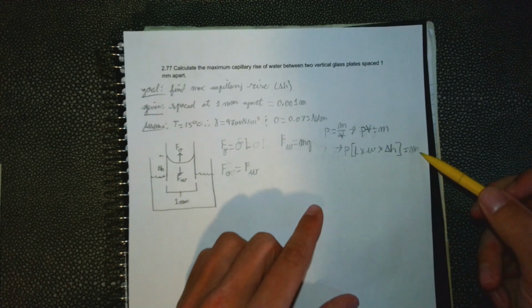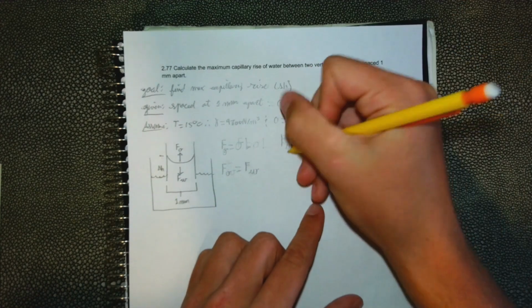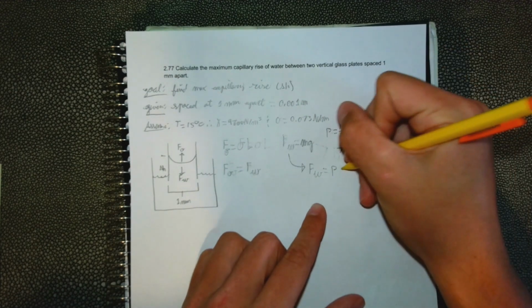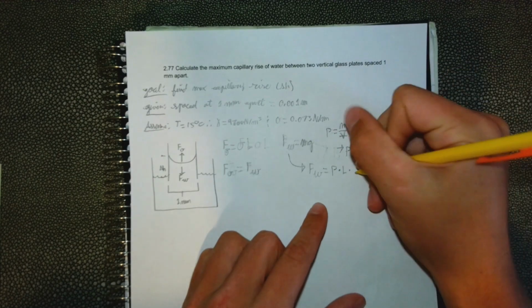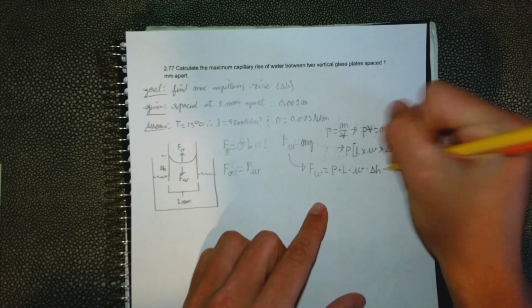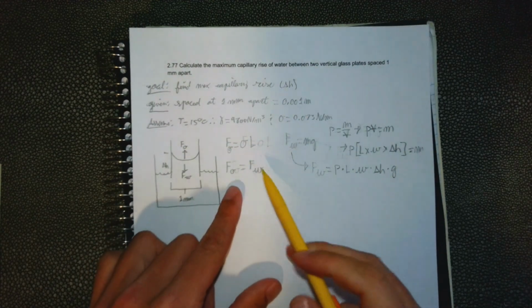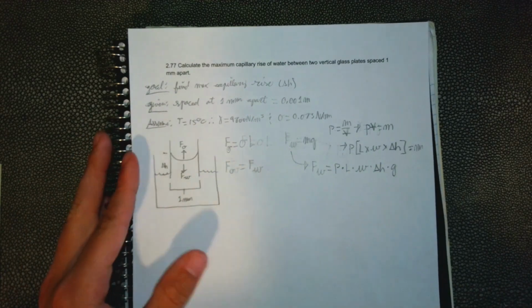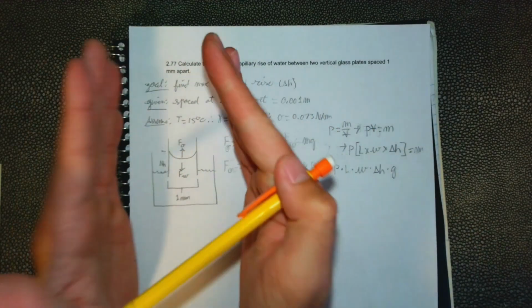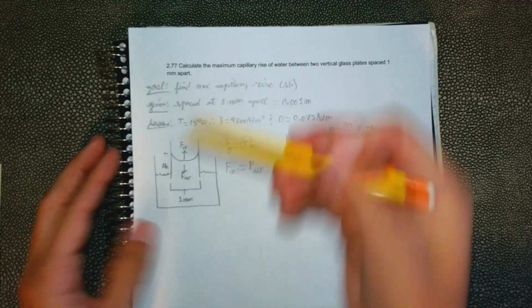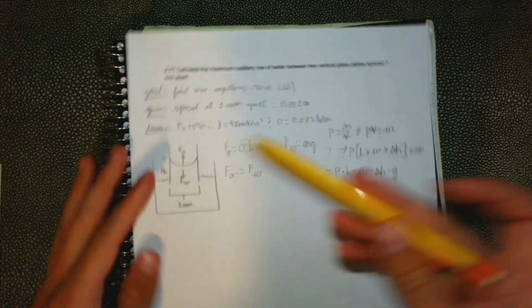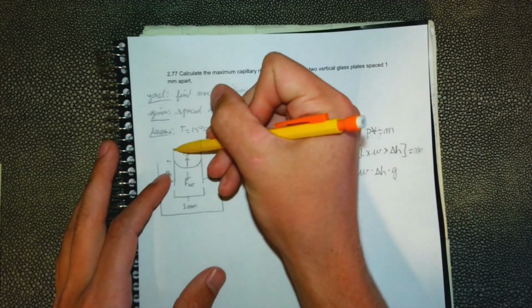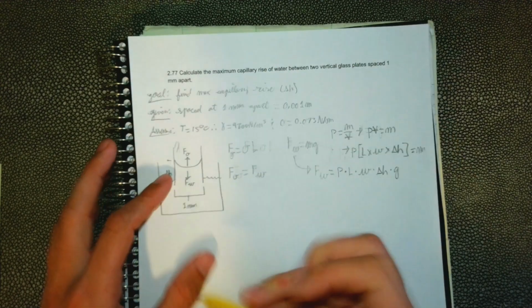So let's plug this in for mass. Rearrange this to density times length times width times height times gravity. Okay, and then we need to rework this to make this represent the wetted perimeter. So when we're looking at this, what is going to be the wetted perimeter? It's just two walls. There's nothing in front. We're not taking a cross section and looking at this. It's really just those two walls. So the perimeter is just going to be the length, how deep this goes back.